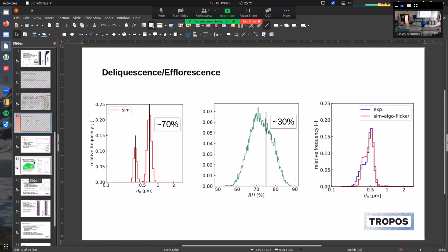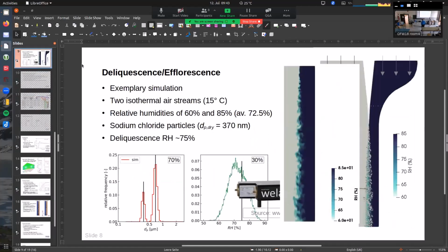For some reason, I have OpenFOAM 10 and I compile everything. I couldn't display the particles. For some reason in ParaFoam, there's no kinematic cloud display there. You have no way to display it. I don't know if you encounter the same problem or you have some tricks to make it work.